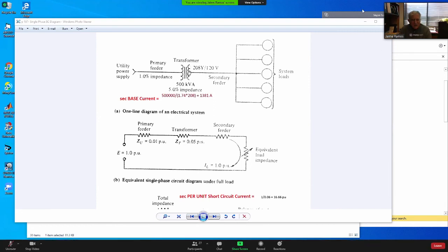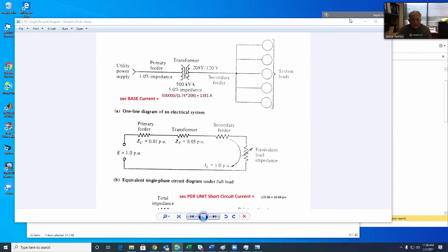So if you imagine this transformer to be the transformer at the high bay here at the engineering building, and the power substation to be a substation located in McCall, between University Avenue and Junior. So all the wiring is 1% impedance, and then the transformer has 5% impedance.